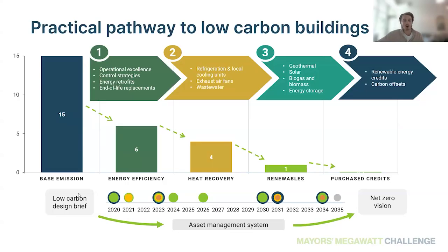So this is the low carbon design brief. This is the site visit, the data collection, understanding the history of the building and how it operates. The operator interviews are very important. If there's any BAS data, you can collect data through that. But the operator interviews help you understand operationally what the hours of operation are, the building type, and how the building is being used.